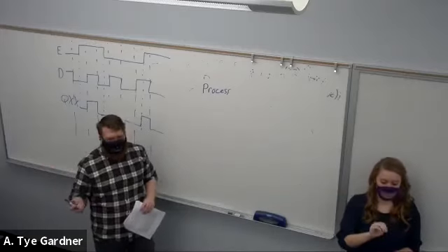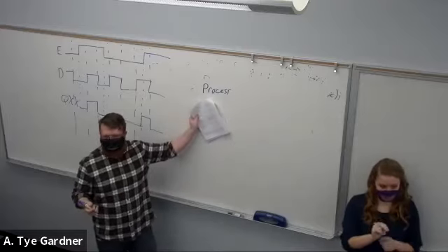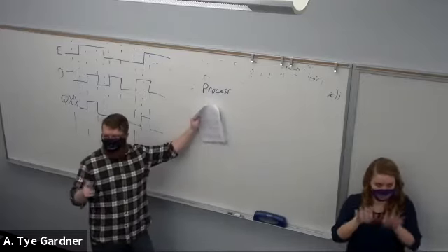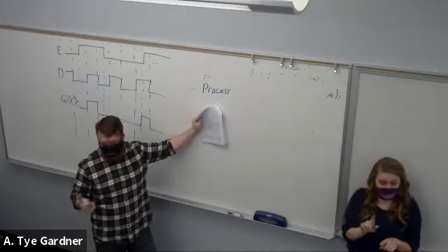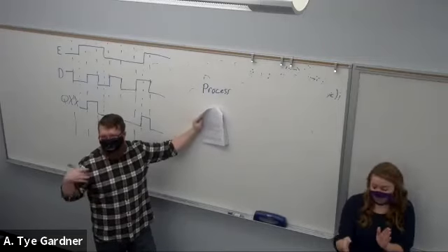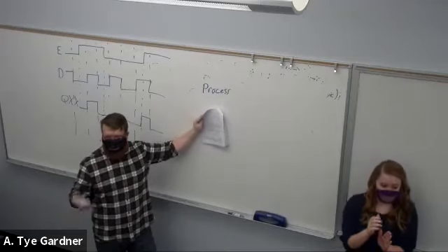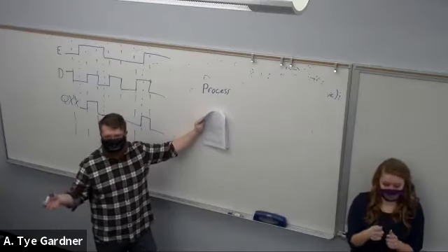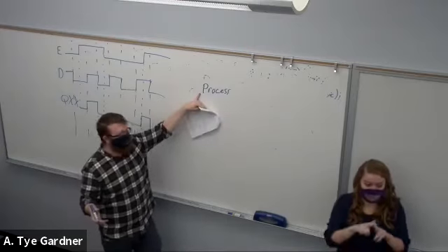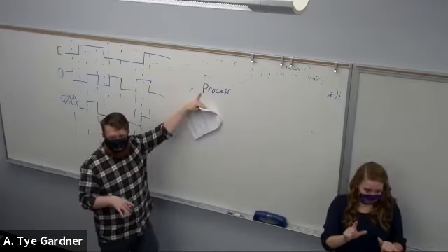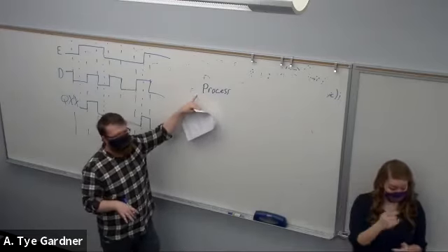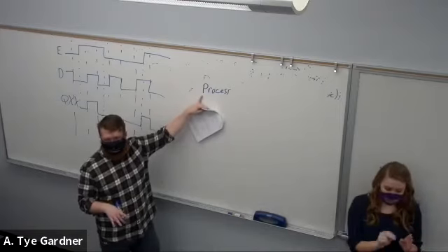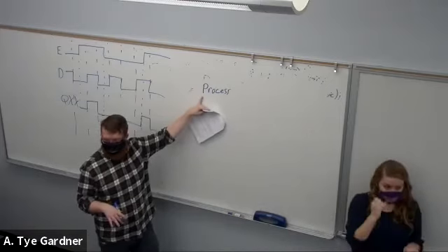There's a mux implementation that uses a process. So you might go, oh, that's a sequential mux. It's not. It would get implemented, once you made it with the VHDL tools and put it in a real circuit, as a combinational circuit. So just because it's a process doesn't mean it's sequential, but it means it could be. If you don't have a process, it can't be.